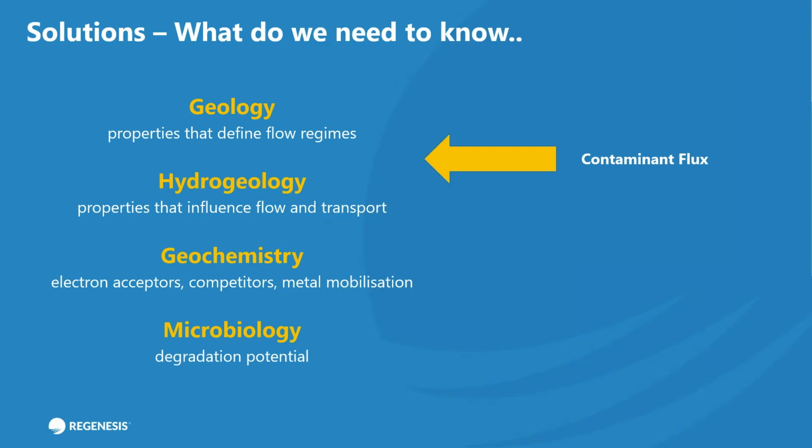Now, one of the methods that I favor, if it's technically feasible, when it comes to fractured bedrock sites, is the installation of permeable reactive barriers, or a series of permeable reactive barriers, or PRBs, across the site, utilizing what can sometimes be quite a high flow regime, so something with a significantly high seepage velocity across the site, to provide sequential treatment. As that plume moves across the site, you get comparatively cleaner water migrating off-site, so you're managing risk that way.